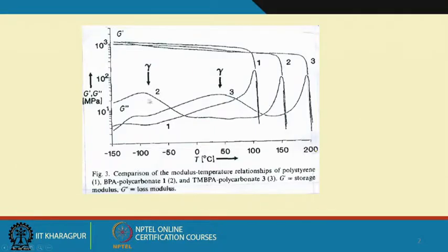So, there is still some motion in the chain, albeit a small number of atoms involved, much below glass transition temperature. If you think everything is rigid below glass transition temperature, think again, because this is not always true. Of course, at glass transition temperature, maybe 50 or 60 atoms in the backbone together start to have their motions freed up at a higher temperature, so that you have a big effect on G prime. But even much lower than glass transition temperature, you still can have motions.